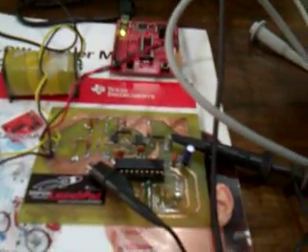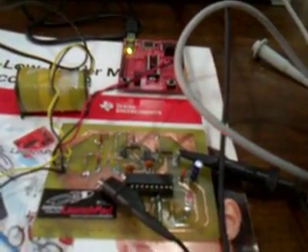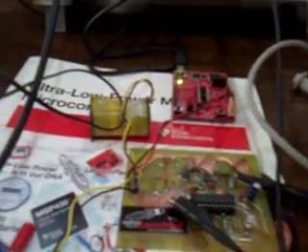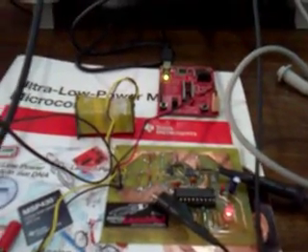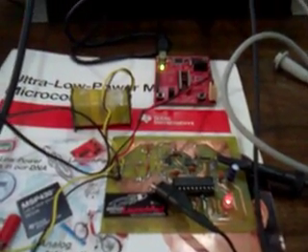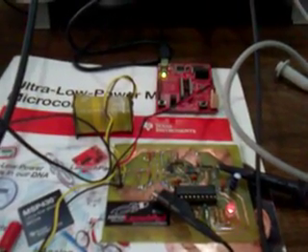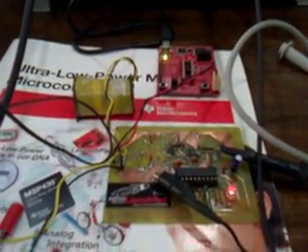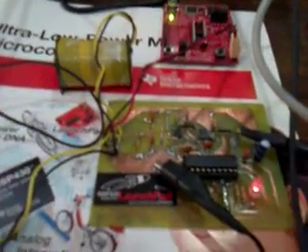Once the fault is seen by the service personnel, using a magnet, the service personnel can easily reset the microcontroller using the reed switch. The circuit has a few capabilities: it senses Imax, it senses the rate of change of current, dI/dt max, and it detects the fault based on Imax and dI/dt max, and the settings of Imax and dI/dt max can be easily done by the switches provided on the board.